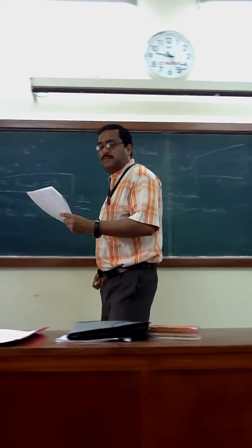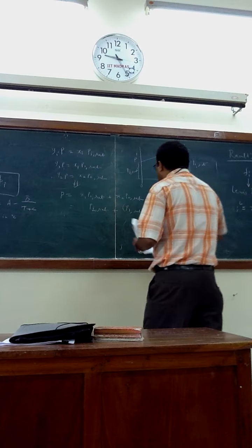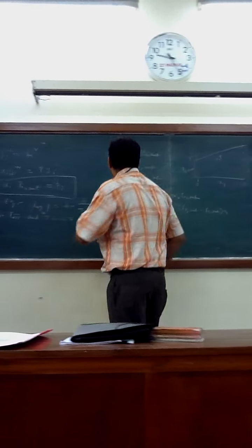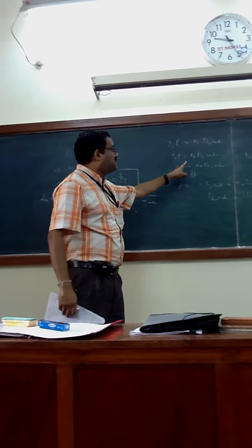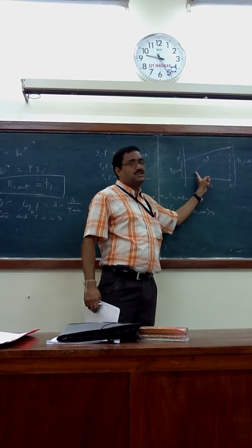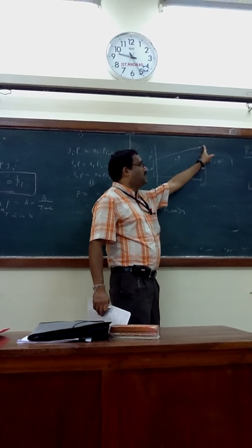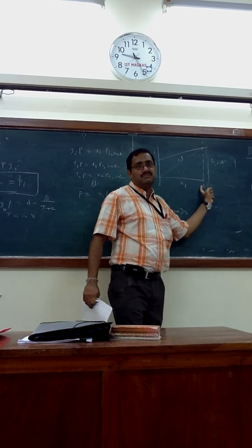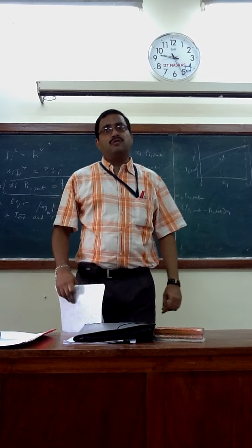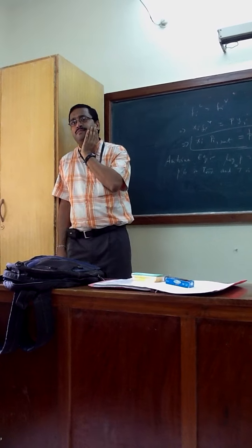From this equation, everything is coming. If you want the partial pressure, this is y1 P. y1 P is x1 P1 sat, which passes through the origin with slope P1 sat, and it converges there at x1 equals 1. Similarly, how will the y2 P curve be?